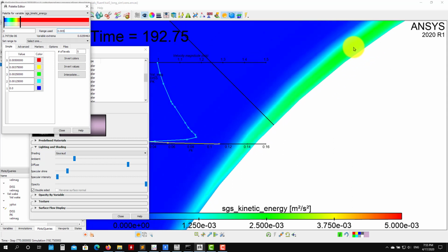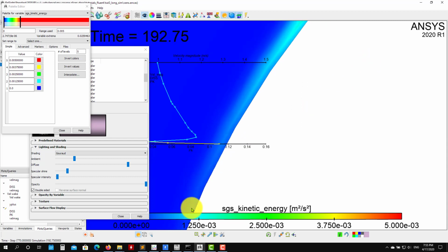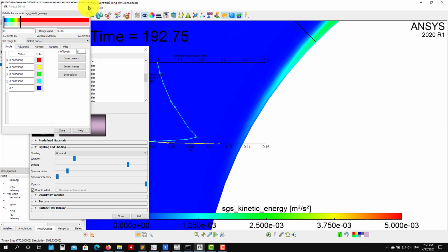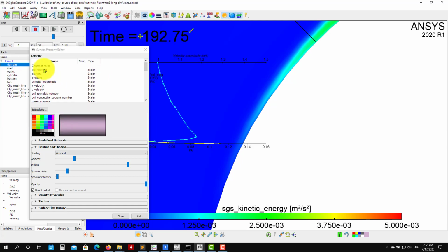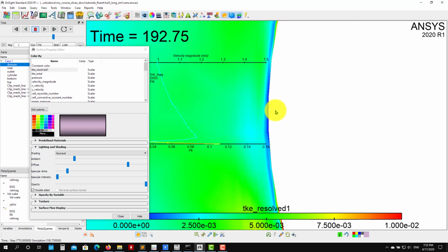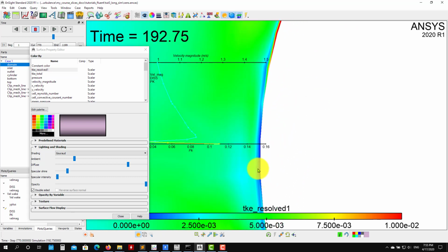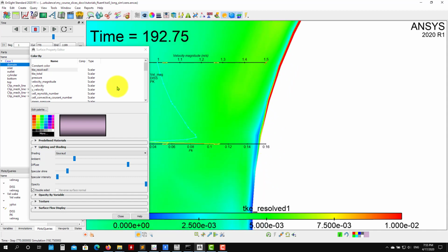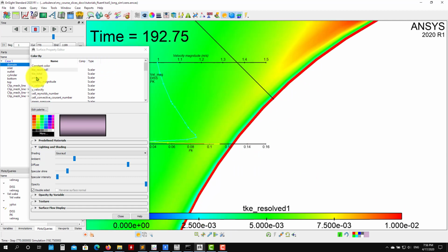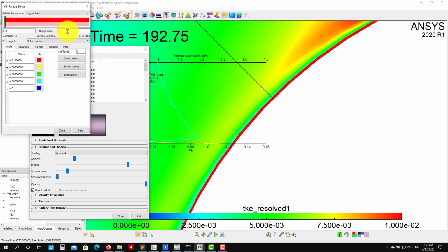All this area here is kicking in, and here, at this stagnation point, this part is laminar. See that we don't have fluctuations there. So this is the grid scale, the modeling part, and then we have also the resolved part. The same idea. You go close, see that it's 0. You don't have any fluctuations there, and then you start to grow the perturbation. Again, here I am putting values. This does not necessarily mean that this corresponds to your boundary layer or where you have the turbulence. You need to find those regions.